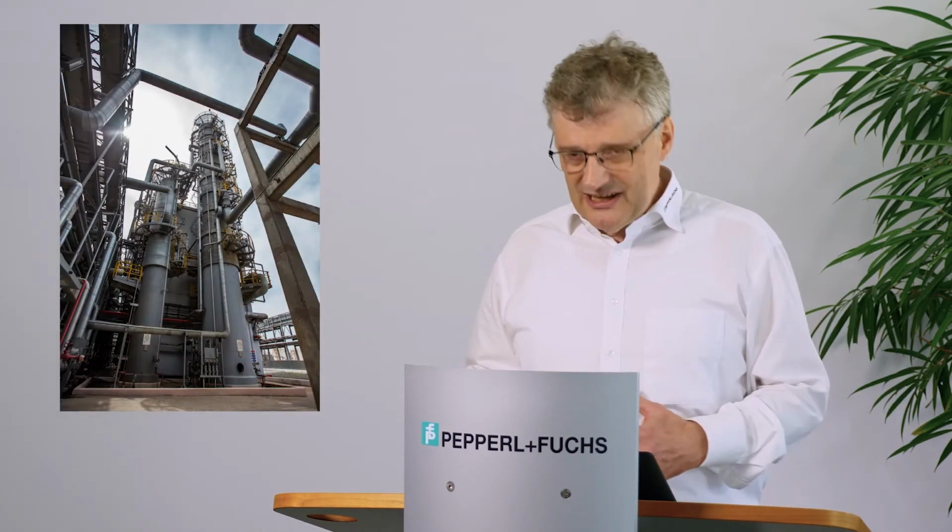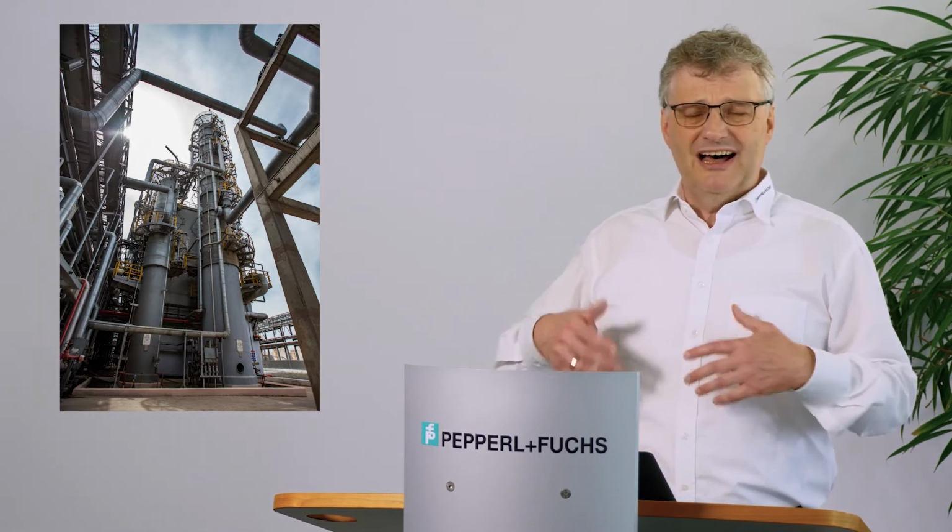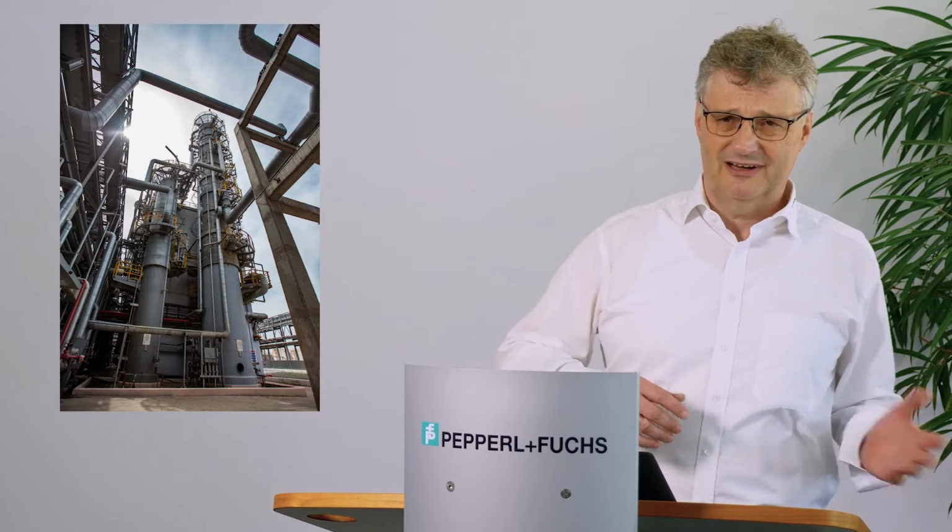In manufacturing industries, Ethernet has made its way. It is state of the art for communication. Why don't we see that in process industries? There are very good reasons. Process automation has a different environment. Plants are huge compared to factory plants. Just imagine a distillation column, I don't know, 30 meters tall, or the fact that we see quite frequently explosive atmospheres in process industries. And also our users are used to having two wires to connect an instrument rather than having separate cables for data and power.